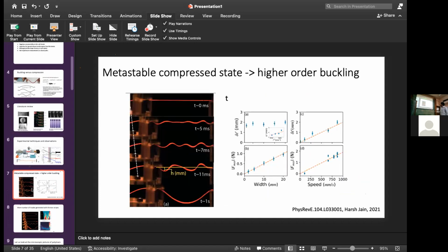I can build dampers out of this kind of system. I'm just giving theory. If you are building a damper, then it will directly go into the buckled state. But if I pre-stress my rods, then whatever projectile, let's say, is hitting from the left-hand side, higher order buckling will cause more dissipation of the projectile force that is coming, and more energy will decay.